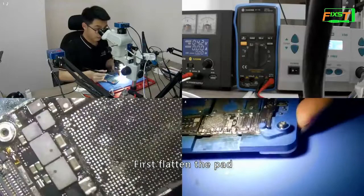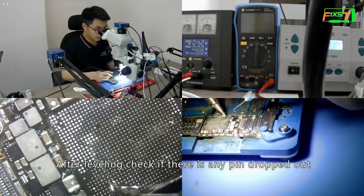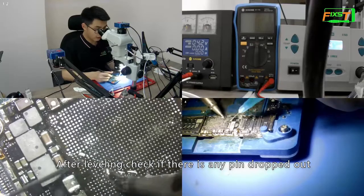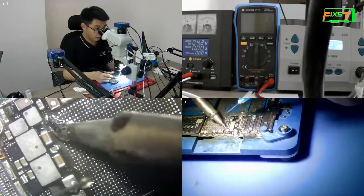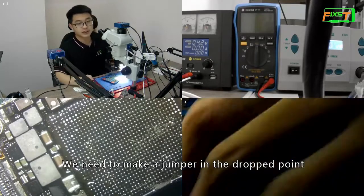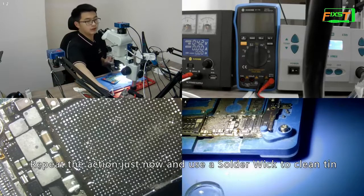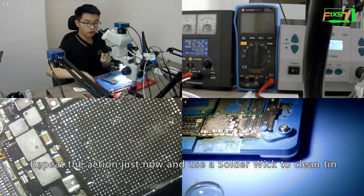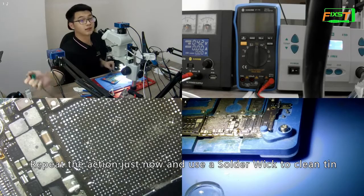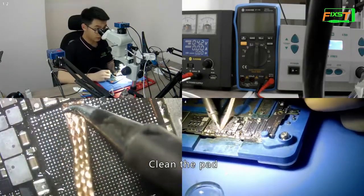First, flatten the pad. After leveling, check if there is any pin drop out. We need to make a jumper at the drop point. Repeat the action just now and use a solder wick to clean the tin. Clean the pad.